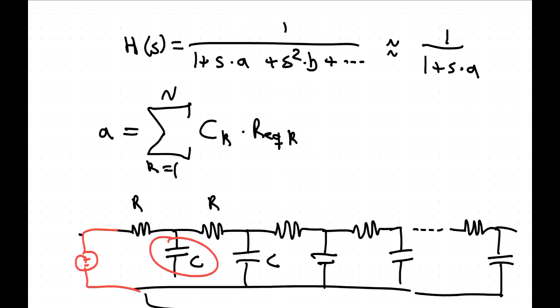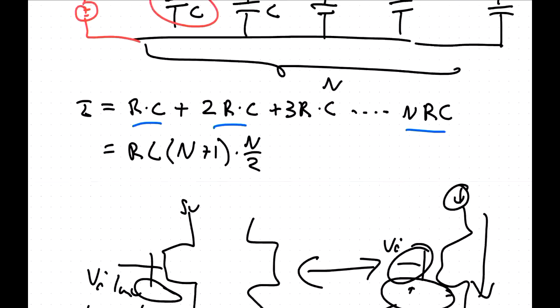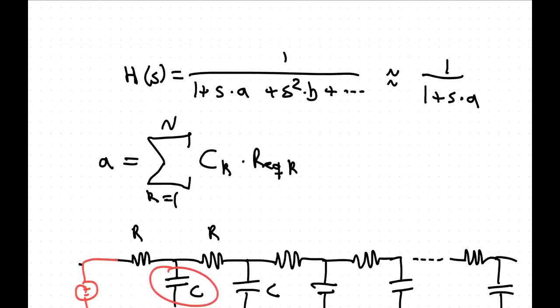If you make a first order approximation, so you have a single pole system, then that factor is 1 divided by your angular frequency. We can find that by taking all the reactive components, which are normally on-chip capacitors, and finding the resistance they look into, and then summing them all up, and then we have a time constant. So that is really what we did last time.